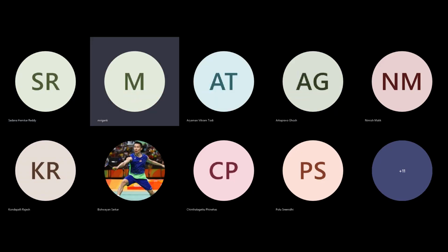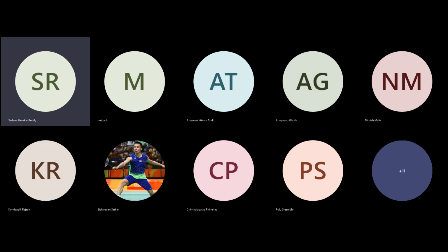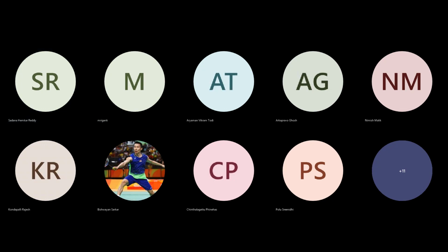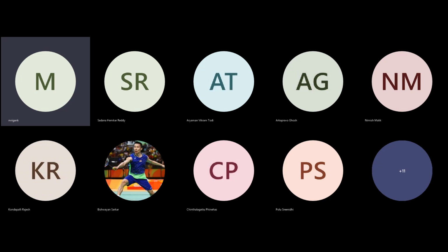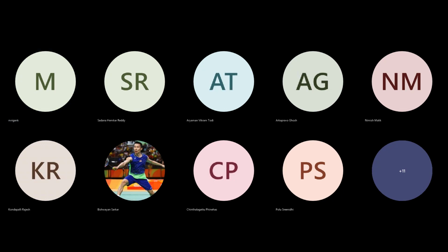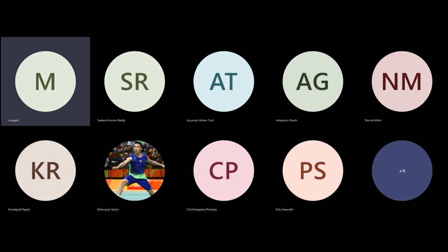Sir, in general, what will be the maximum value of W or L that we can go up to? That depends on application, right? In certain designs, like when you are designing an LDO, low dropout regulator, you need a MOSFET to supply current to all the other circuits. There, the W by L requires maybe even 1000 micro, that means 1 milli. That is because it is required to supply that much current.